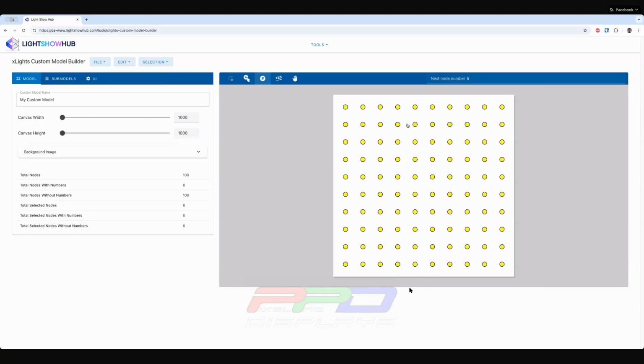And then you'll see this new one here, which is add numbers to nodes by dragging a line. So what this does is as I'm dragging, you'll see it's drawing a line of a specific thickness. And while I'm drawing it, I can use my wheel on my mouse to change the width of that line. And what that's going to allow me to do is draw a line and auto number as I go across. So this makes numbering quite a bit easier.